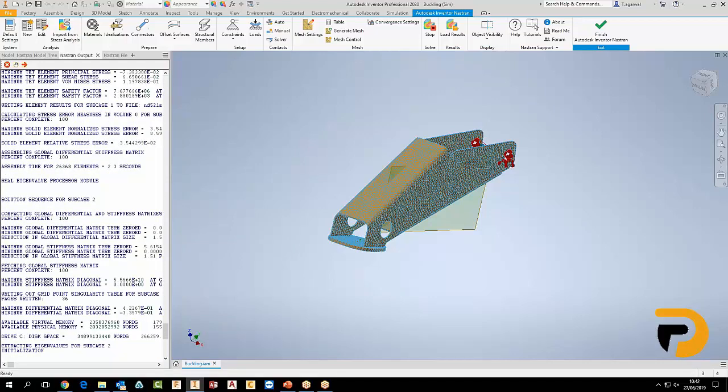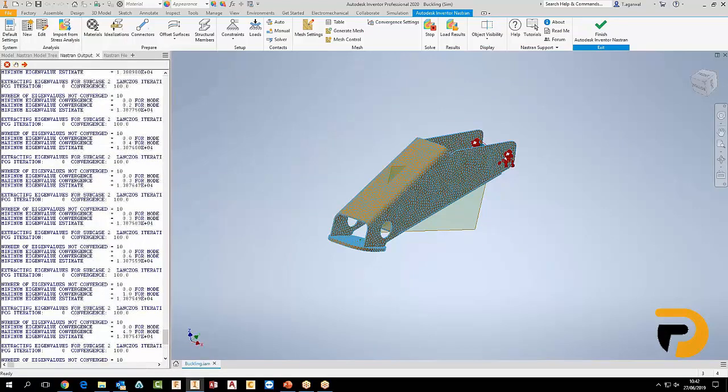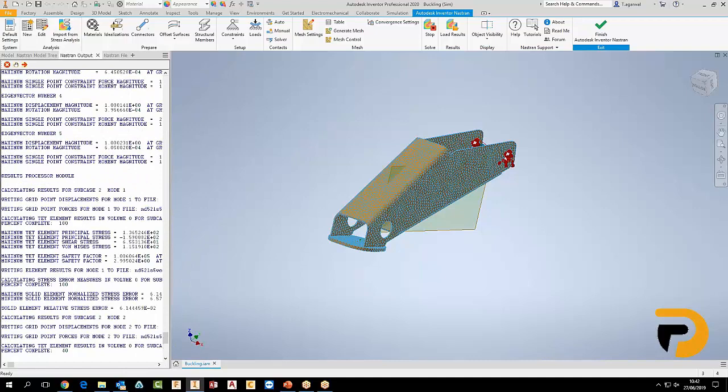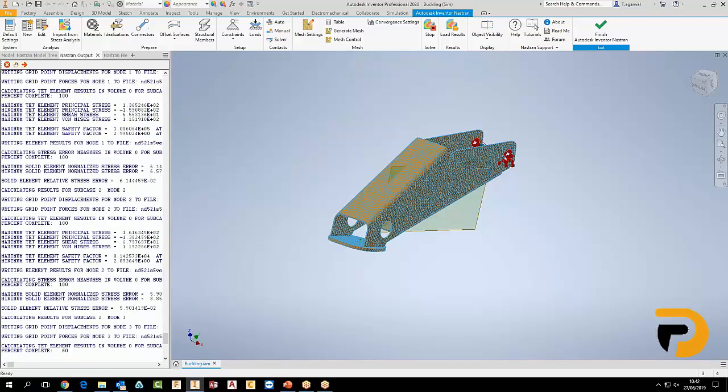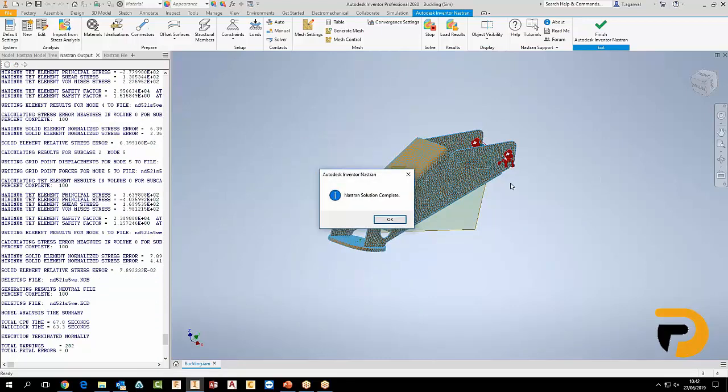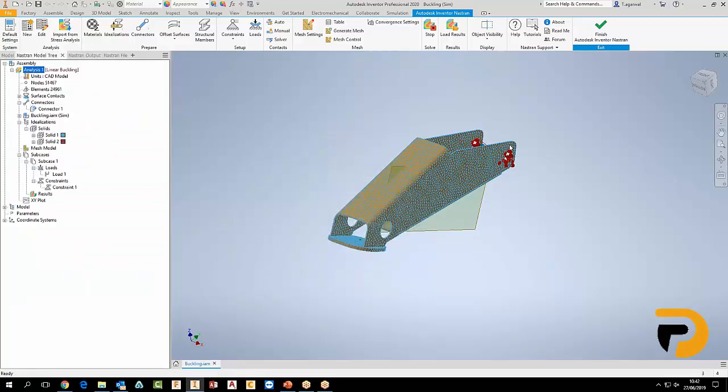So you can see very quickly we can do, as I said, bolt connection, shaft, rods, all that kind of stuff can be done and preempted on the model. So we're simplifying the simulation very quickly and easily. And again, we get an accurate result because we have a very good representation of what we're trying to achieve. Basically, that's where the connectors are beneficial, because you don't have to model parts, you don't have to mesh them, you don't have to generate contacts with them. They are just available to you and you can use them directly. Yes. Instead of using a part and meshing it, that just generates more computation time. So that's not good.